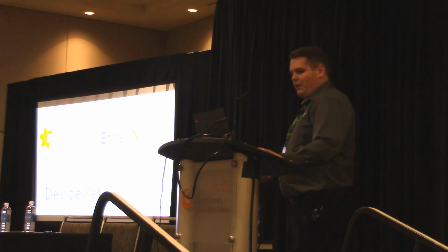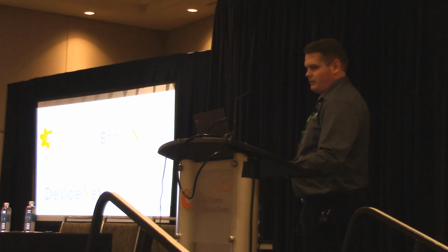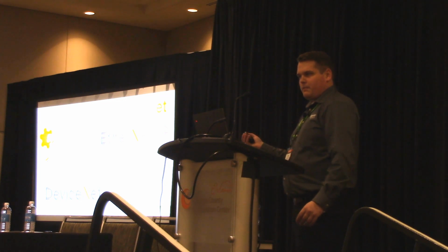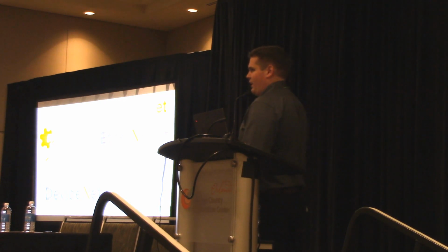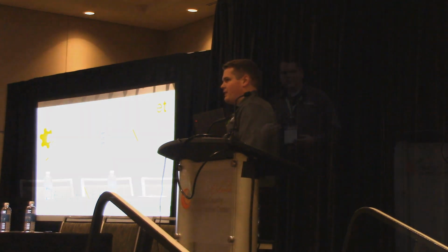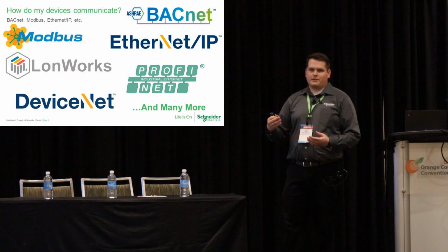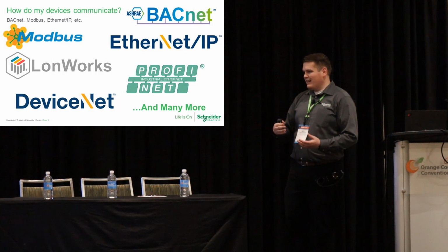PROFINET, I'll refer to some of my notes here, bear with me. PROFINET and PROFIBUS, both very similar. Kind of layers on top of your standard analog signal, so your 4-20 milliamp. It's a communications protocol added on top of those, so less wiring, less field installation, a little bit of cost savings.